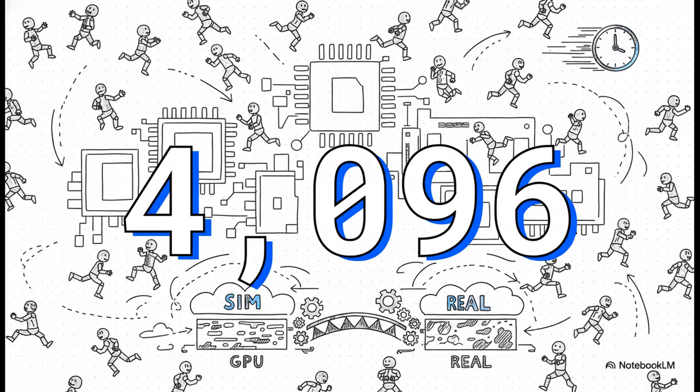We use massively parallel simulators like Isaac Lab or MuJoCo MJX. We're not training just one robot at a time. No way. We are running 4,096 parallel humanoids on a single GPU simultaneously. Because of this massive scale, the system gathers literally years of physical experience in just a matter of hours. The reality gap shrinks drastically because the training data is so incredibly wide, making domain randomization practically free.